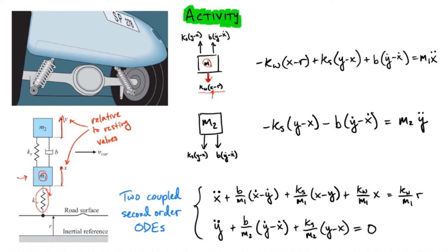Likewise, we've got the spring force and the damping force. These are actually going to pull up, and in this case, they pull up when y is positive. That's why I've written these as pulling up, and y is my first term, that it's positive. Again, if you wanted to, you could switch these arrows around and switch these two and essentially make that, for example, x minus y, but with an arrow going down into the block. So that's essentially the same. Once you have your free body diagram, the beauty is that now you can say that it's the mass times the acceleration.